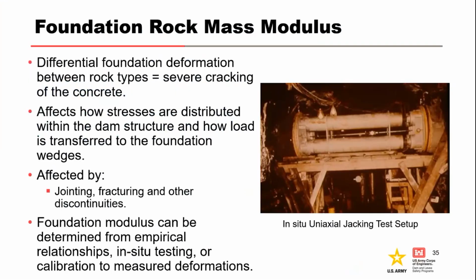Okay, I just have a few slides left on foundation rock modulus. The rock mass modulus is a parameter that describes the rock mass stiffness and resistance to deformation. In other words, it represents how much the rock will deform under stress. So differential foundation deformation between rock types can lead to severe cracking of the concrete in a dam.